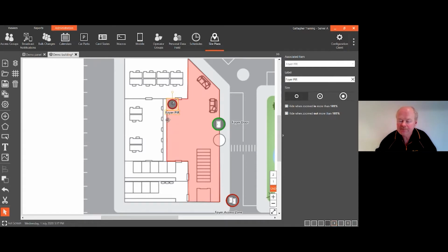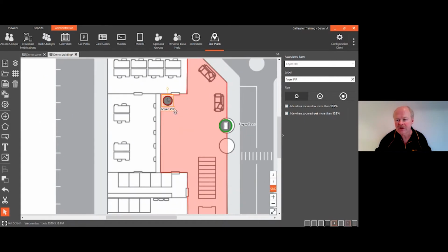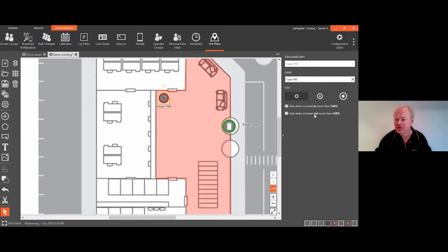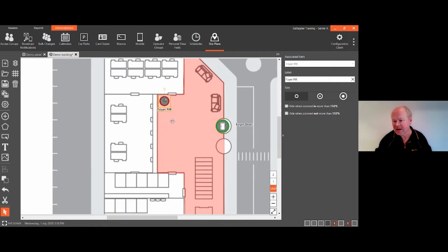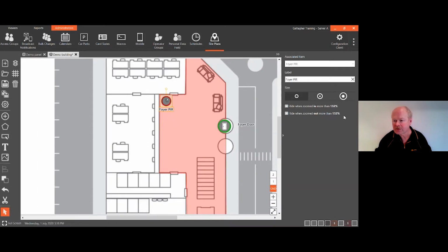Now with that PIR, we want to make this so it disappears unless you zoom in far enough. So if I click on my zoom control, as I step in, you can see these percentages go up. I want it around 140%, 148, 132. It looks like 132 is my best step.